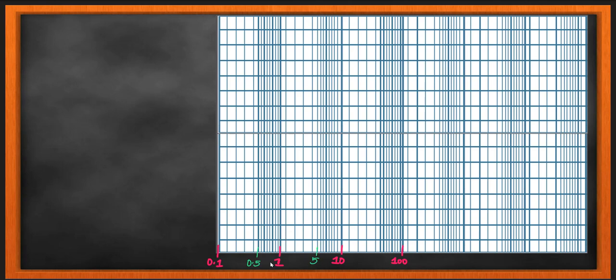Alright. So that is the x-axis, and now I have to plot my magnitude and I have to plot my phase on the same log graphs. You need to plot it on the same graph because you want to compute the phase margin and the gain margin.